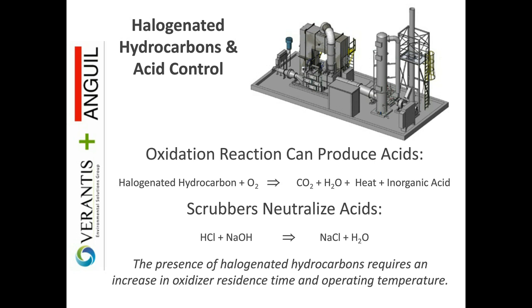Now it creates a number of other concerns within any of these oxidizers, but what it'll also mean is in many cases, a secondary piece of equipment is going to be required to neutralize that acid. And that secondary piece of equipment is usually a wet scrubber. And with that, I'll hand it over to Brian.